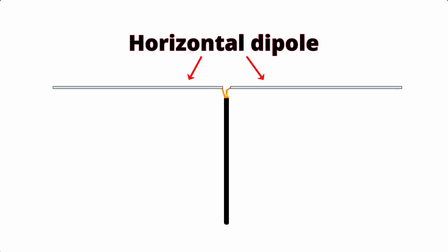In fact, you might even have a better SWR than if you had a choke or current balun, a one-to-one balun, in place. The reason for that, of course, is that rather than any reflected power going back down the coax and pushing on your PA, it's being radiated along the coax on the way back. So of course there's less getting back to the transceiver and the PA to present that return.